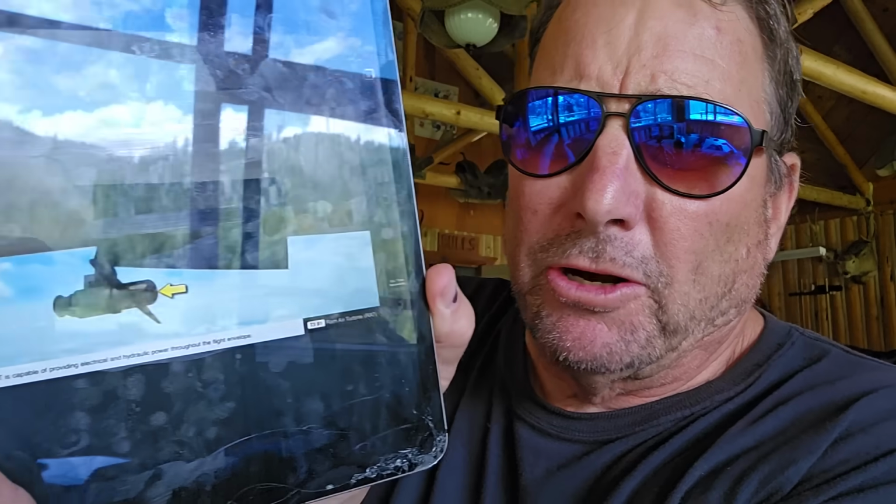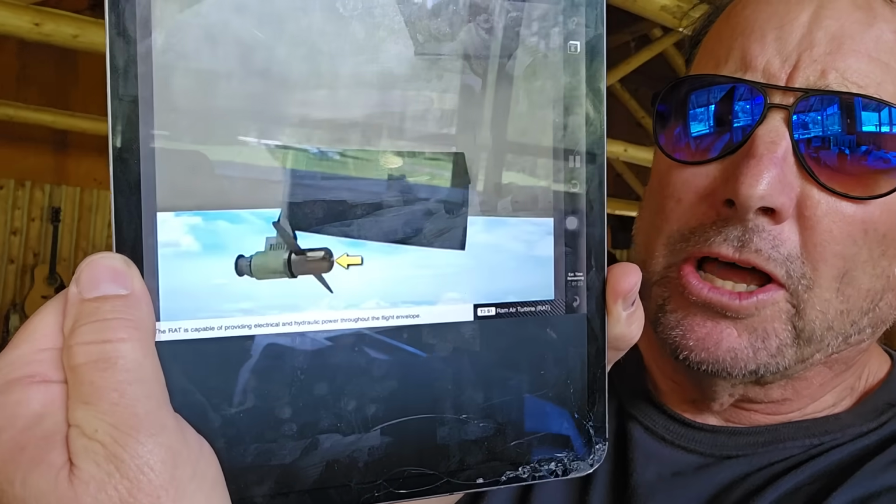So to me, in my opinion, this appears that this jet had some major problems taking off or prior to takeoff. The Ram Air turbine is located right there on the fuselage behind the landing gear. It's a constant speed propeller, so it's a variable pitch propeller to allow it to operate at maximum RPM even as the speed of the aircraft decreases.